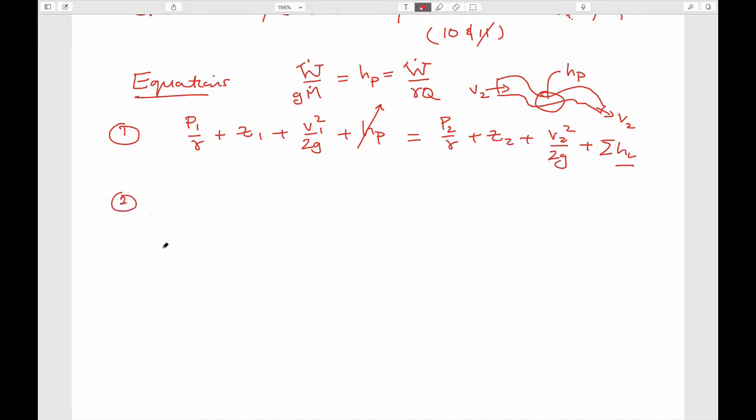The other way to write it is in terms of enthalpies, and so in this particular case, the mass flow rate multiplied by the enthalpies, always between out and in, plus the kinetic term, velocities out and velocities in, and the potential energy term, which is the elevations out and the elevations in.